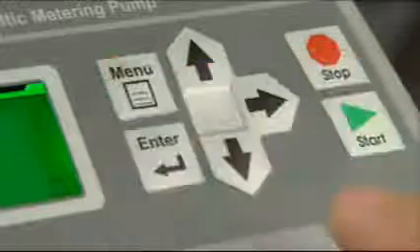Enter the Input Setup menu. Then the Input Mode menu, and then select Frequency Input. Input a frequency value to define a low frequency point on the slope. Note that this value is usually 0. Input the percentage of motor speed required at the low frequency value. Note that this value is also usually 0.